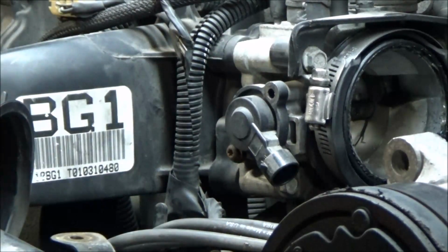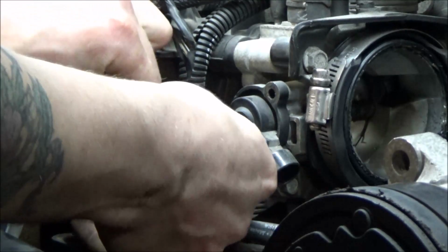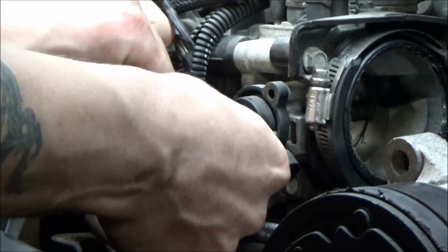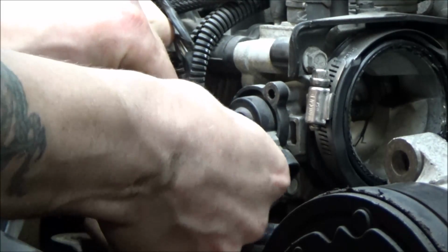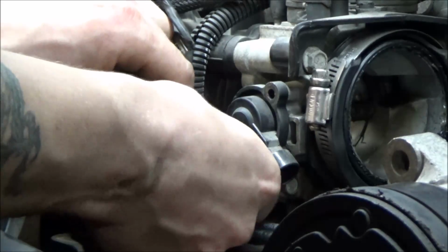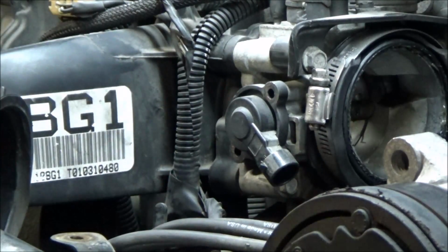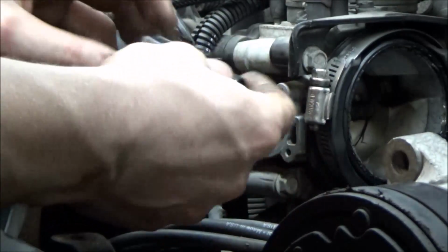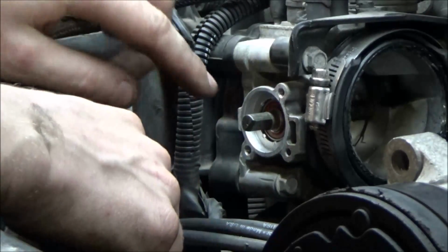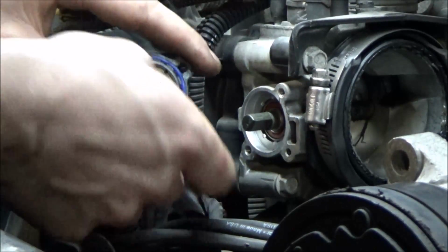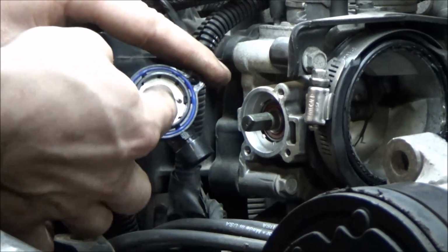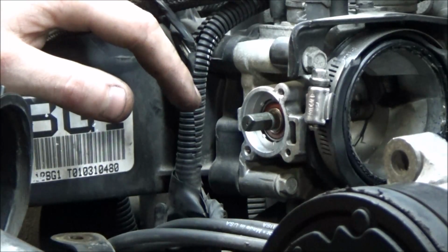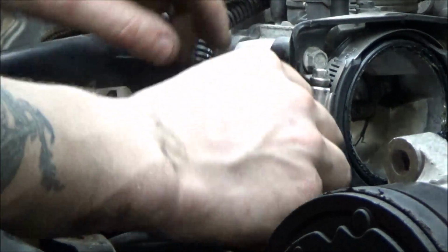But something to definitely watch out for on other vehicles potentially is that you may need to perform a base closed throttle voltage calibration on these to make sure that they're sitting at the right spot. This one, as I said, I don't believe that is the case. The sensor does not appear slotted in any way, and you can't really rotate it off of the shaft. So we can see the shaft here it lives in, guys. The old sensor that we just pulled off, you can see that it's actually keyed to the shaft, so you can really only put it on one way. So we're just getting that old sensor off of there. We're going to put this new sensor on.